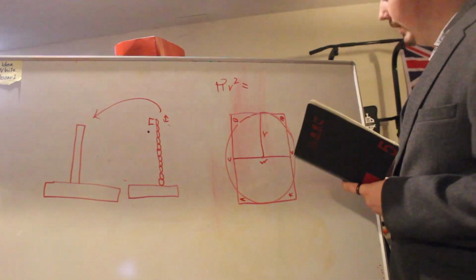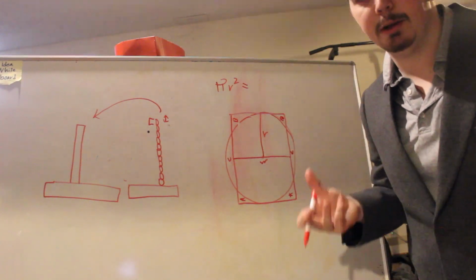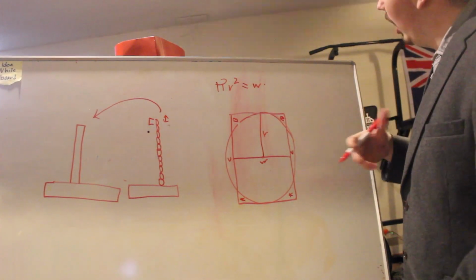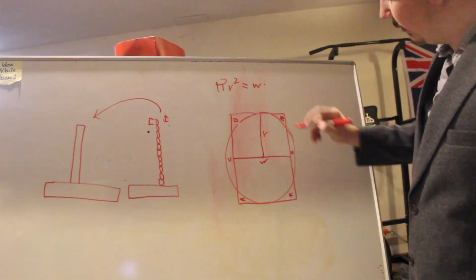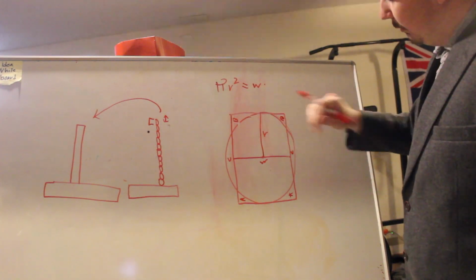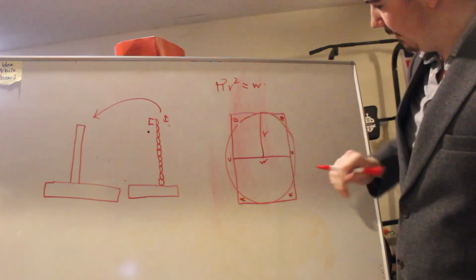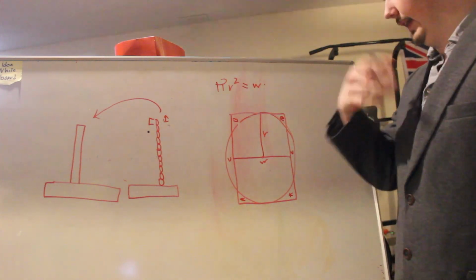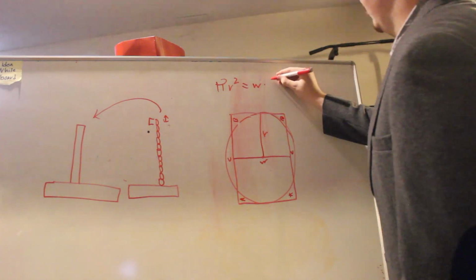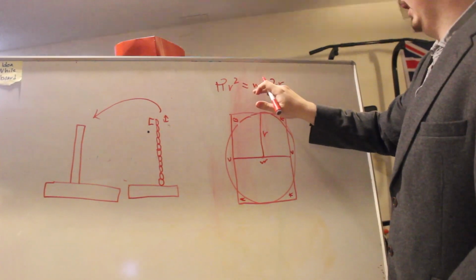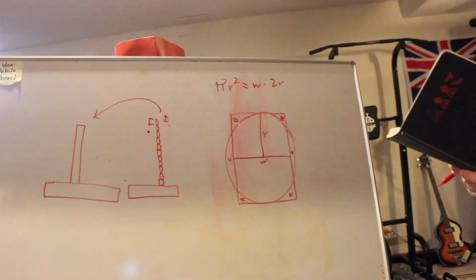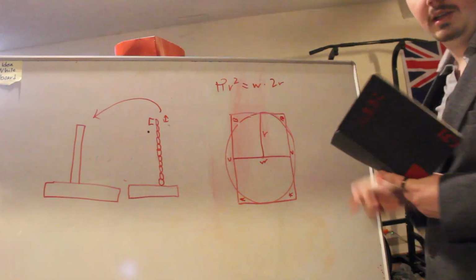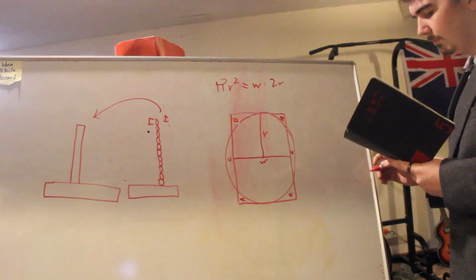Well, we don't really know what our width is. That's the value we're trying to find. So let's just keep that as w. Do we know our height? Yes, we do. Because of the consistent layer height, it will have to be r. But that's only half. We want the diameter. I don't want to redefine it as diameter for our equation purposes and later canceling out, so we're just going to call that 2r. So we don't know our base, and we have our height. We've got some consistent equations here. We're trying to find our w, so let's algebraically solve for w.